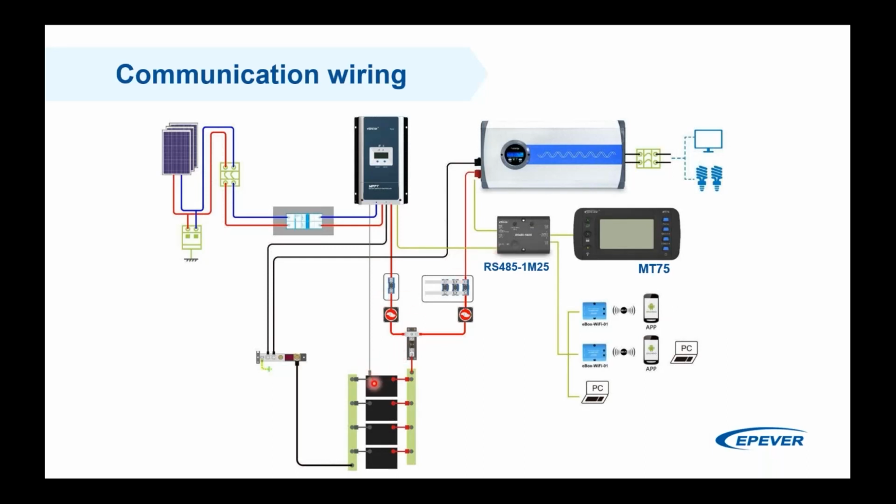As an example, we have a battery temperature sensor connected to a charge controller, for instance. And it tells us that we should stop charging the battery if the temperature rises above a certain threshold. So it's important that this value is communicated between the system, or this inverter can be shut off if the battery voltage goes below a certain threshold.